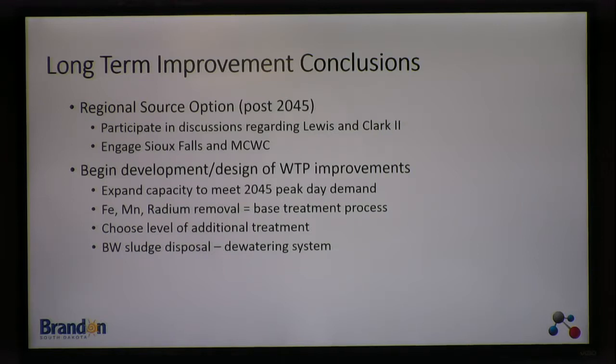Well, quite frankly, it's limited in South Dakota because you have to have the opportunity to discharge the waste, right? So Yankton's new plant, the HDR facility, has RO in it. That's the most recent. Windstone is a small community that's part of the Clay Rural Water System. It's a small community north of Sioux City. They have an RO facility with iron and manganese removal ahead of it. Quite frankly, that's really what Yankton is. It's RO with iron and manganese removal ahead of it. Those are the two that come to mind.